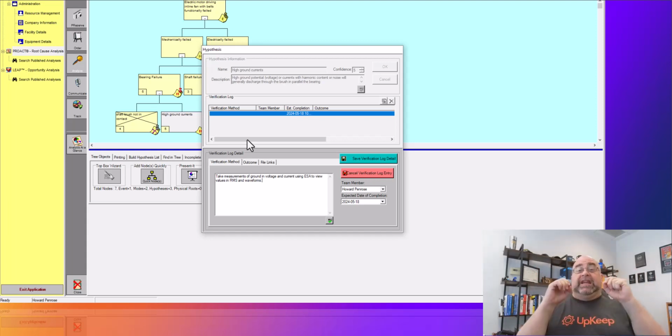but mostly what I want to do is put an actual insulator with the bearing, such as a ceramic. So I might have a ceramic ball, I might have ceramic coating on the outer race. I don't like the inner race because ceramics don't expand or contract, and the shaft of a motor tends to expand and contract a fair amount.